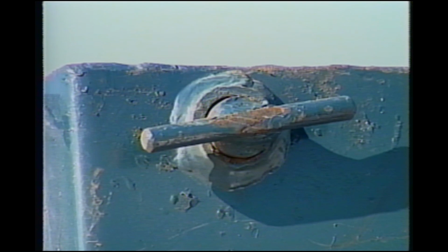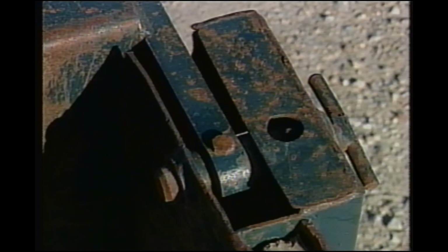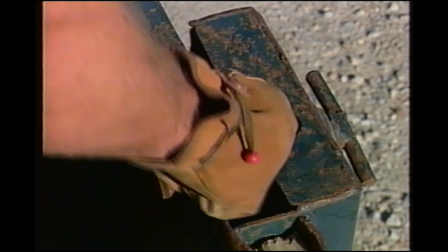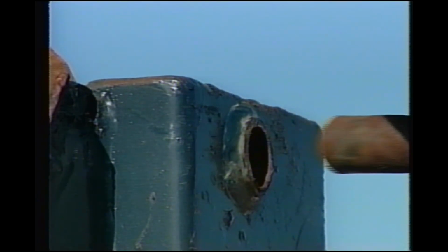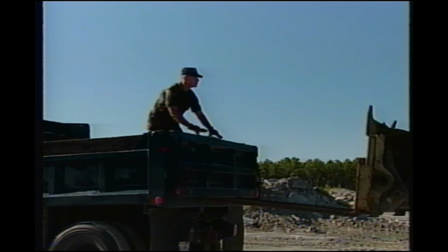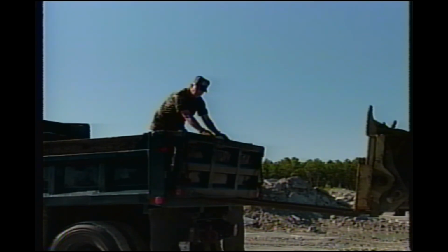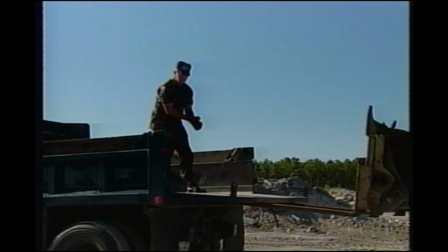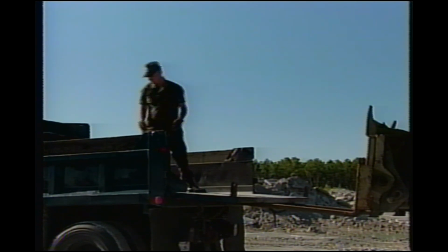Located at the top corners of the tailgate and the bed are the hinge pins. These pins hold the tailgate on the bed, or they can be removed to take the tailgate off. Remove the safety locking pin and slide the hinge pin out on each side. With both hinge pins removed, the tailgate should still remain in the upright position. Carefully rotate the tailgate out until it rests on the forklift forks.